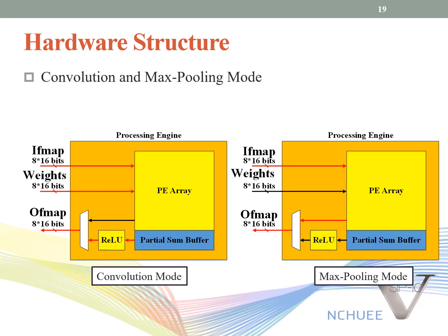If the next layer is convolution mode, the partial sum will add bias, then do ReLU before sending out to the global buffer and SRAM. Else, if the next layer is max pooling, the result of the three rows of operation will be sent to the first convolution buffer directly, and so on. The next result is sent to the second convolution buffer.